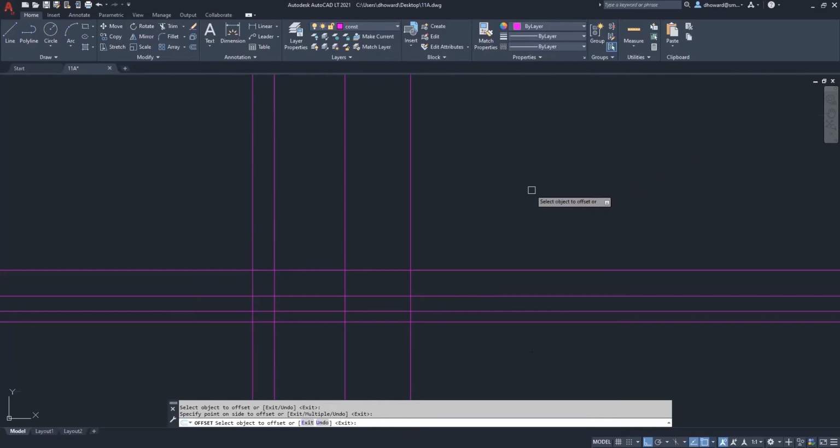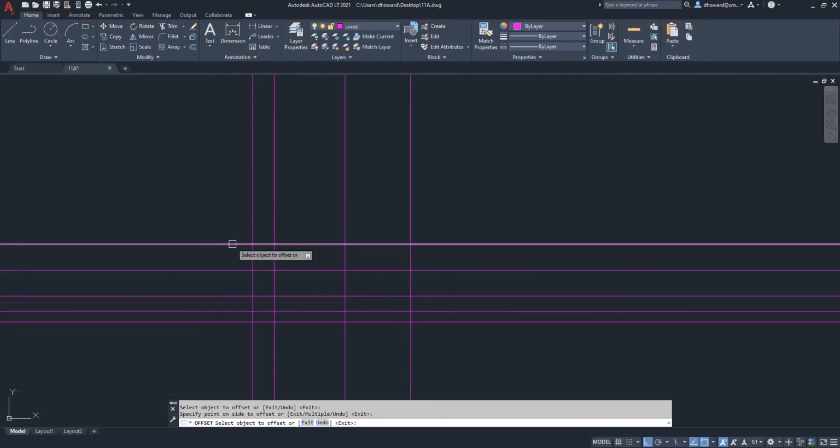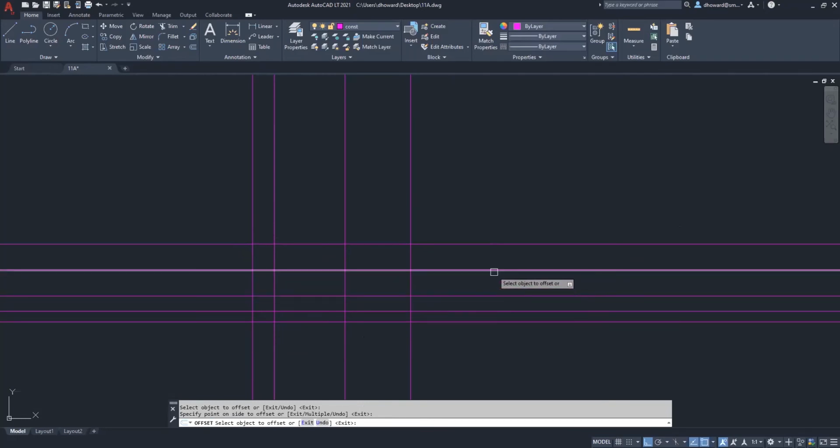And the last thing is the final height of this object. And that is given by the radius of the arc that makes up the final height. And that distance is 3/4 of an inch from this line here. So I hit enter to get out, enter to get back in, and type 0.75 or 3/4. I can click this line, and then there you go. So now I have all of the construction lines that make up that front view.